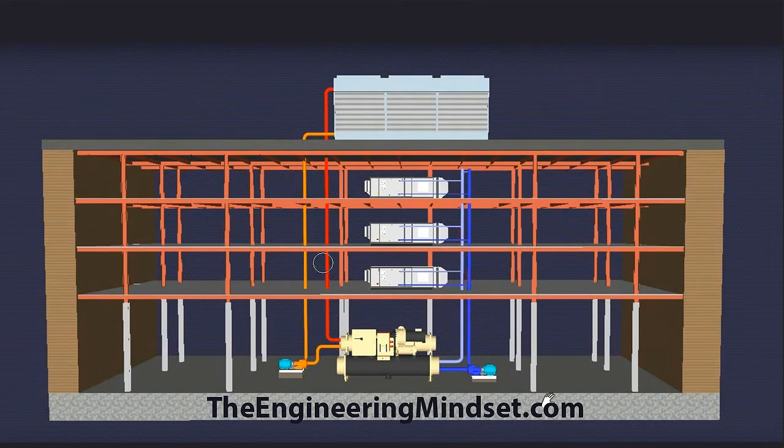That is then pumped up. They're two separate systems, by the way. You should know this from the other videos I've done. But that heat is then sent up to the cooling towers where it's rejected, and the condensed water drops a few degrees Celsius or Fahrenheit, and then returns back into the condenser there, ready to pick up more heat from the building. So we're going to go along and look at how this system now works.